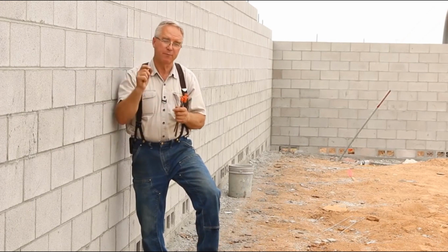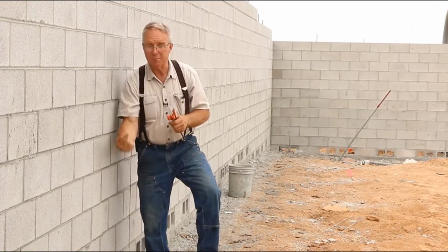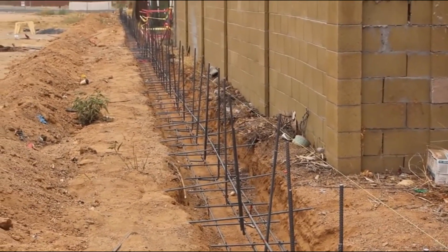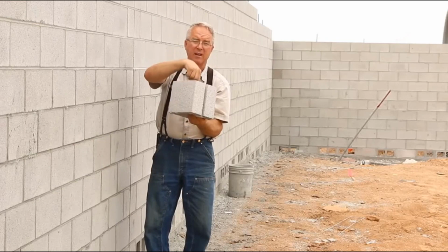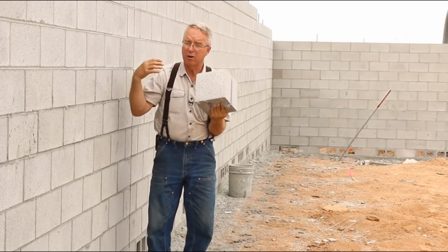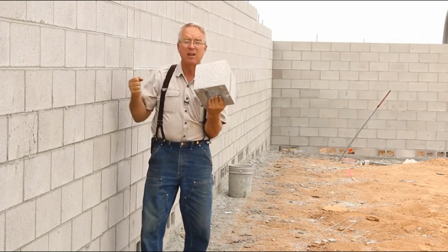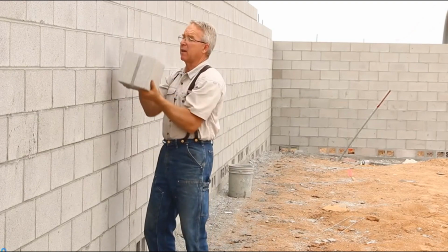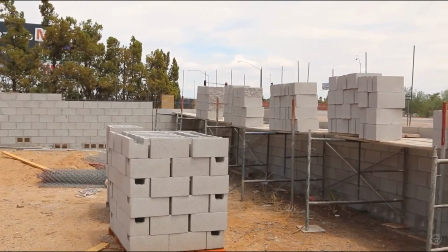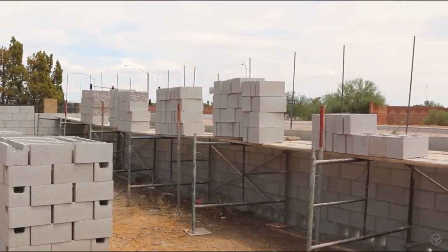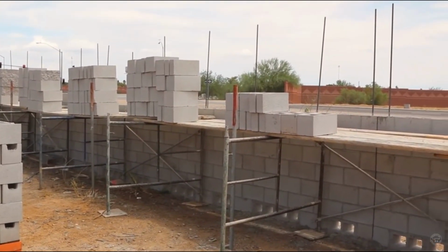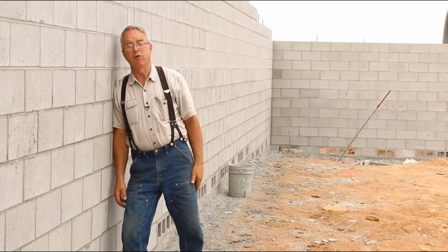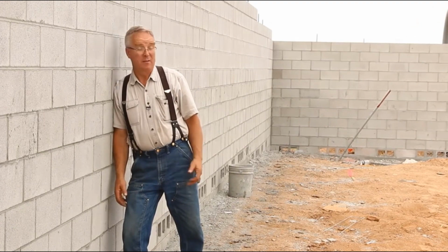Not only is rebar placement very specific in the footing, but when it comes out of the footing, the verts that come up in the air in a block wall are even fussier than in a cast-in-place wall, because the verts have to hit inside the cell of the block. So when those masons are slamming these blocks in here, they're not having to hickey or bend or distort those rebar verts into the cells as they slip these over the verts while the mud is on them onto their bed joint without tearing the world apart. So the rebar verts have to come up in the right spot. These guys did a great job of making that happen with really minimal form work, minimal messing around. They know how to do it.